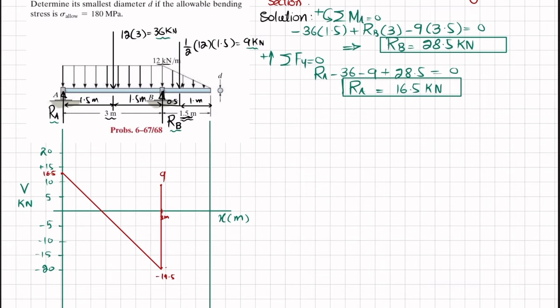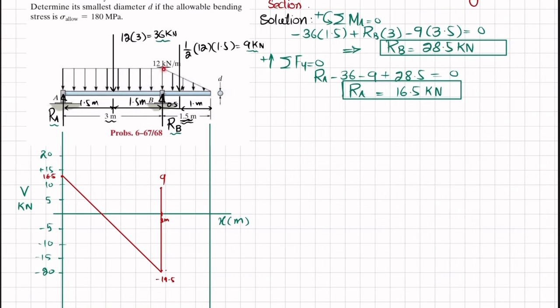And here you can see you have a uniformly decreasing load, so this will be equal to, that is, you can see that is 9, and that will be downward, so it will be minus 9. So plus 9 minus 9 will bring it to 0 at this point. And you can see that this load is a 1 degree line and slope is decreasing, so its shear force will be a second degree curve, and it will be like this.